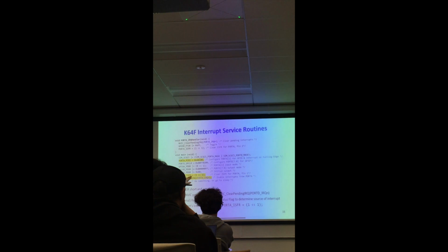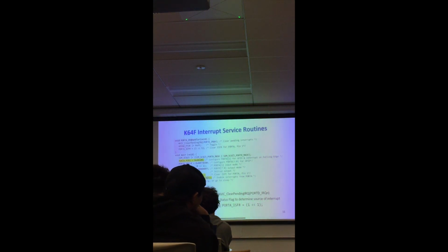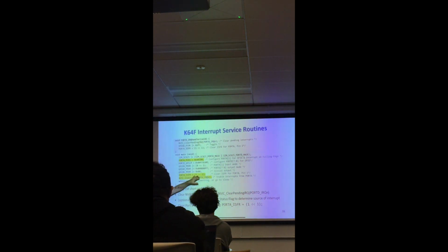That's what this line actually does. Port A, apparently on pin 1, we have to clear the flag. I do it intentionally here, even though, since this is just the beginning of the code, that bit will be cleared anyway. But I still do it, just to make sure, not to depend on it. What if some other routine or configuration modified the bits by accident? I still enable it by clearing that bit.